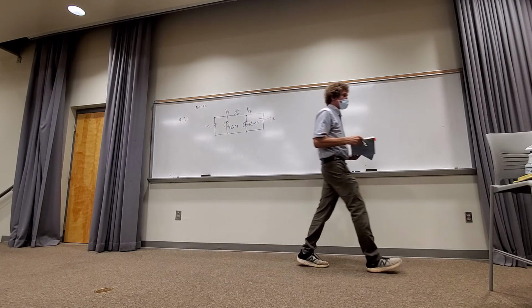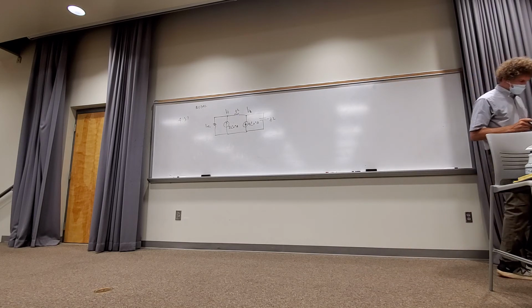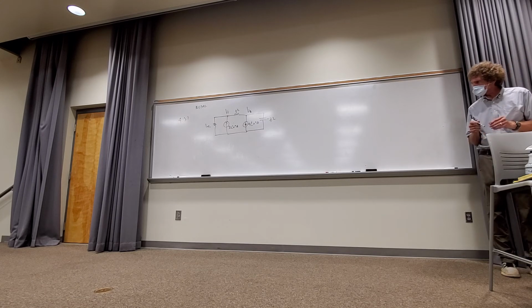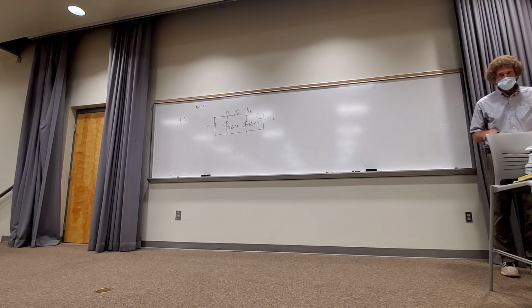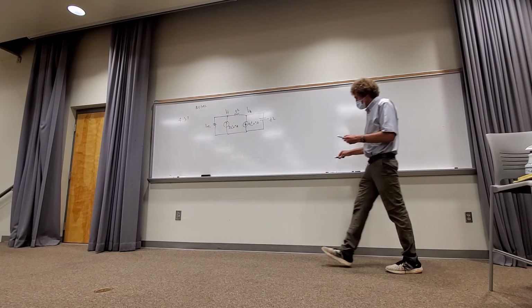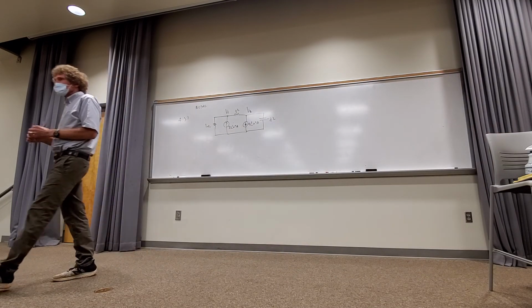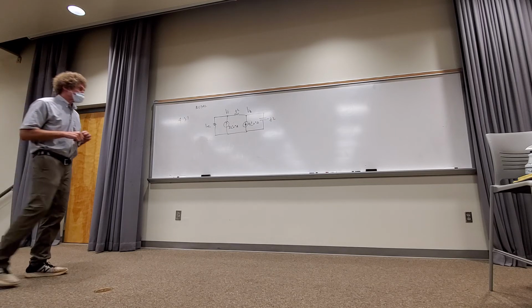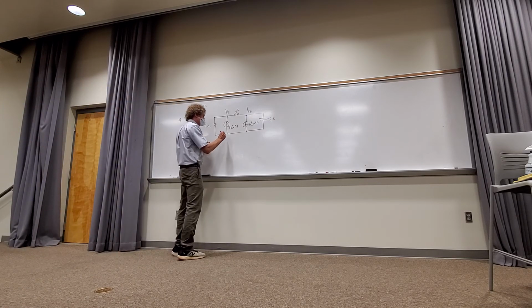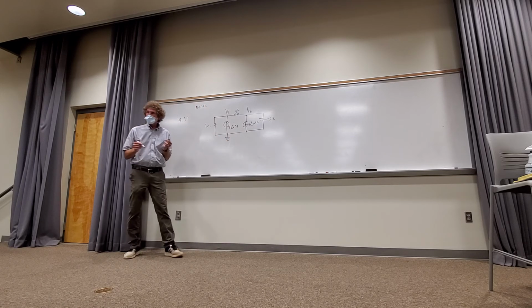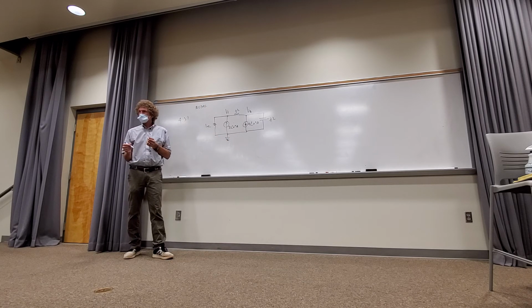All right. Let's see the question. Yeah, they just want V1 and V2. This is nodal analysis. So, have a look here. What's the first thing we do with nodal analysis? Usually, if there's not a ground, you better put one in. There are no tricks for me here. Put it on the one common link that ties everything to ground, okay?